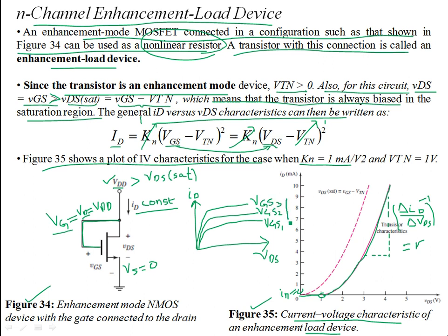As you increase your VGS, you are also enhancing the channel, so there's more drain current. The same thing goes on over here. For each VGS, you have more and more drain current. Since the gate is short circuited to the drain, VDS here is your VGS. So as VGS increases, the drain to source voltage increases, and your current is also increasing. The space charge density of the channel is increasing, so the current grows beyond the threshold point. This is VTN. So that's the idea.